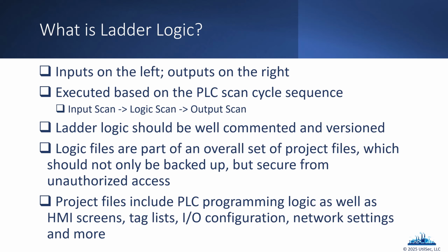LabShock, which we use for a portion of our labs in the course, uses OpenPLC, which is actually programmed in structured text. But for the side workshop, we're going to do ladder logic, and then maybe one day come back and take a brief look at structured text and some of the other ones that are out there.